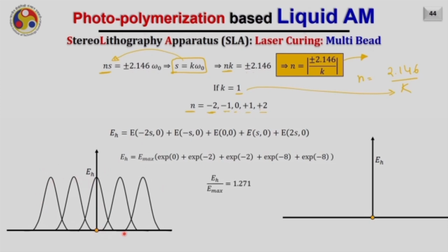These 5 passes are shown here. So, in other words, any pass, for example, there is another pass here, 6th pass. For that pass, this particular point which is of our interest will be out of the zone of influence. Hence, we can say that this point is within the zone of influence of these 5 passes only. Hence, to find out the energy absorbed by this point, we can start from this end, that is the energy